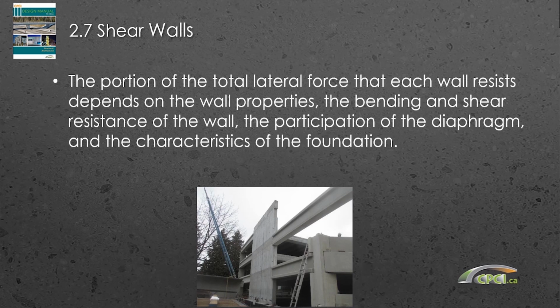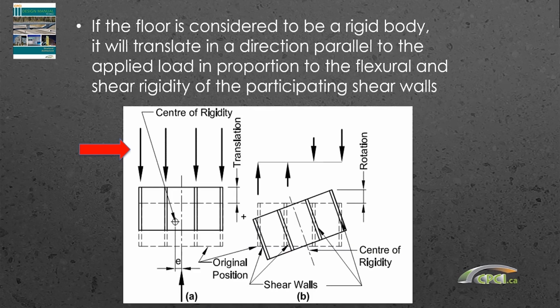to each shear wall. The example in the manual is really showing the traditional sort of rigid body effect of if you had a very rigid diaphragm, in this case with 4 walls, and you were pushing it and all of those walls move the same amount. All of your shear walls are the same height, same stiffness, and they all deflect the same amount. As shown on the left, you would have equal reactions in each shear wall.